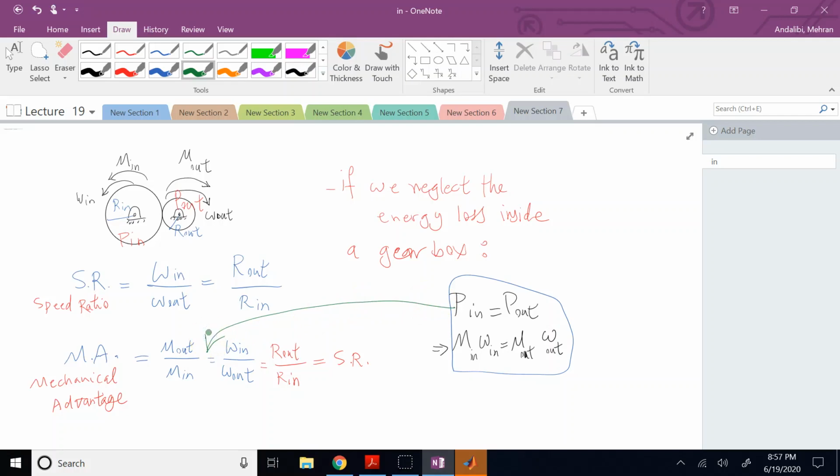So just wanted to tell you that. And clearly that's what I mentioned when you put a manual car in low gear. Low gear means big radius, output compared to input. So when you put it in low gear, it's kind of the opposite of this. The small one is the input, the bigger one is the output.